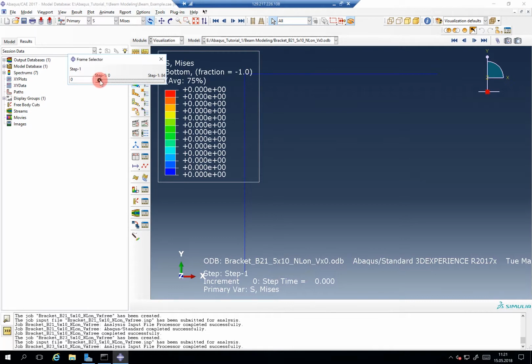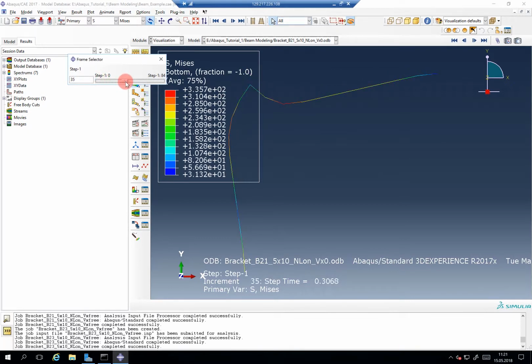So this is quite important to understand. Whenever you change the geometry of a part, so for example here you change from vertical to horizontal, it will, so to say, weld this connection with an infinitely stiff welding connection. So this will stay 90 degrees because you geometrically ask for it.